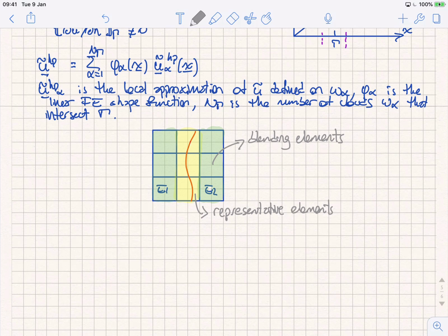So your enrichment function can go to 0 at that node, but if it is non-zero in the blending element, then you may have issues. So it really depends on the choice of enrichment function whether you have issues in blending elements or not. In fact, there was a paper that was proposed to address this issue altogether by extending the area of enrichments and multiplying with an extra enrichment function, but that's another completely different story.